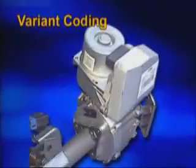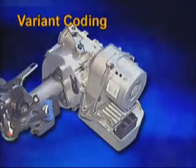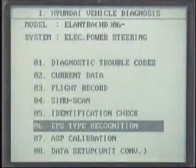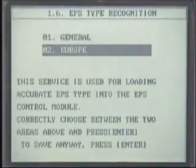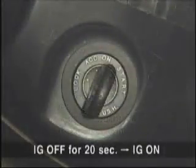When a brand new MDPS is replaced, the variant coding should be set. This is the logic considering the difference of steering effort per region. In the power steering item of the scanner, after selecting the EPS type recognition, select the General or Europe. After being IG off and waiting for 20 seconds, set IG on.